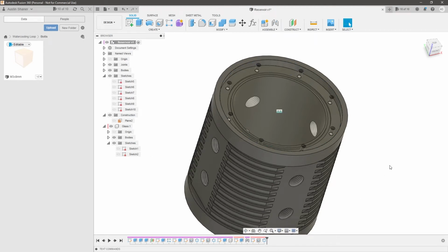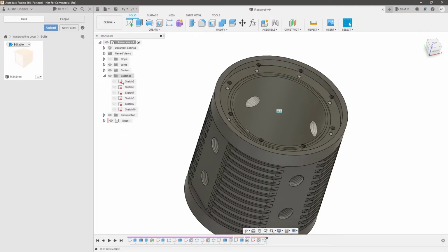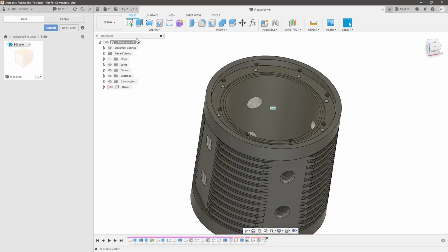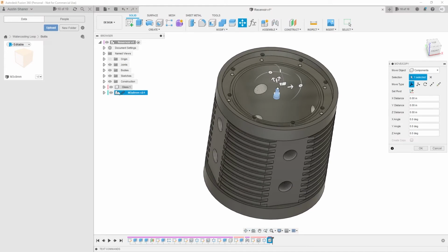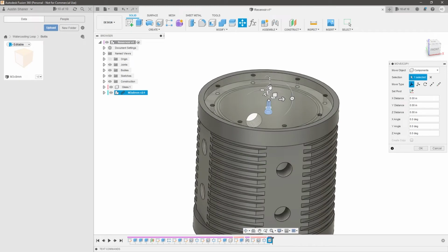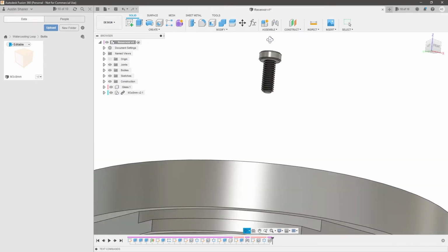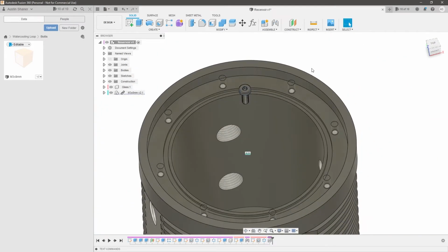So let's delete that component insert, and let's shorten this up, and let's make sure you're clicked on the highest level assembly file right here. So not this component, but this one. And now let's insert that into here. So now it's going to insert it underneath glass, but not inside glass. And that was the problem we ran into. So let's rotate this around, and let's rejoin it. This bottom ring right here to this one, join.